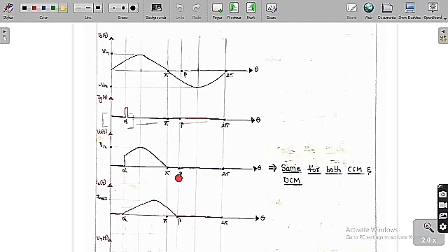But after pi, we are going to give a negative voltage. As we give a negative voltage, the thyristor is off, and there is also a freewheeling diode. Because of this, the freewheeling diode is going to become on. As the freewheeling diode turns on, the output voltage will be equal to 0, but the current is going to decay in a slow manner.